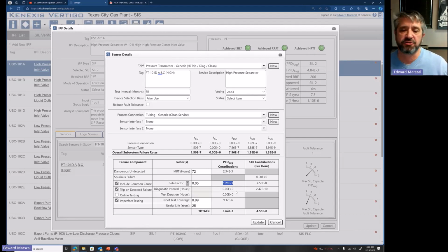So let's go back to that level transmitter. So let's say that level transmitter is running at 12 milliamps, 50% level. And then one scan later, the analog input signal goes from 12 milliamps to 0. Okay, a functioning transmitter will never go to 0. If it's 0, it will go to 4. So because you went from 12 milliamps one scan to 0 the next scan, you know that the transmitter is not voting to trip. It's broken. It's busted. So what do you do when you detect that that failure has occurred?